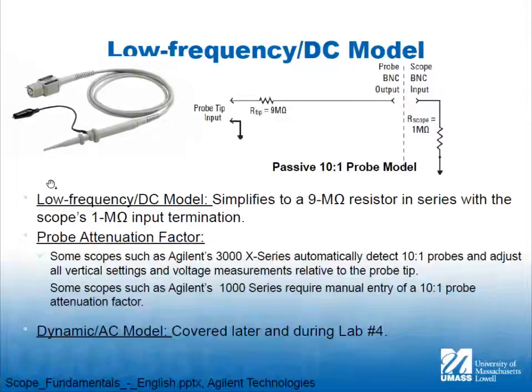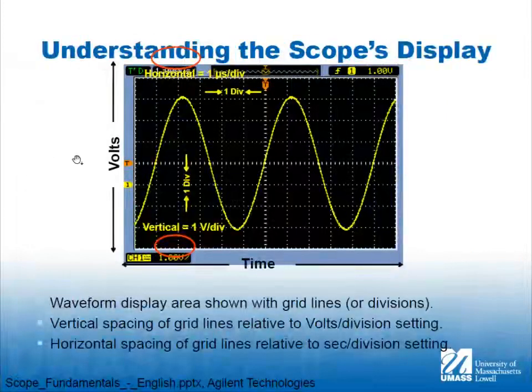Okay, so there's the low frequency probe. And then what does this do? My red circles shifted, or the picture shifted, but I'll point it out. So here's the display of an oscilloscope, and there are 2 settings here. One setting is the resolution for the channel. We only have one channel showing. It says 1 volt. That means each one of these divisions is 1 volt. So here's the thing. We don't care about this tonight because we're not measuring volts. We're measuring ones and zeros. So our measurements are not going to use a large number of bits.